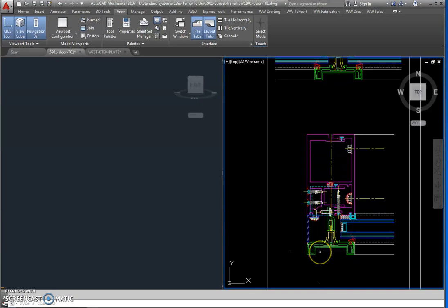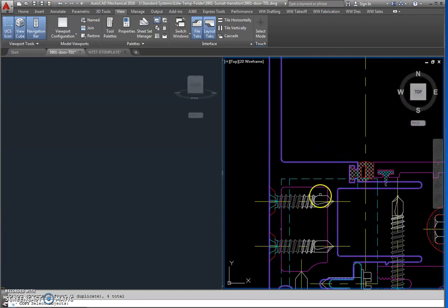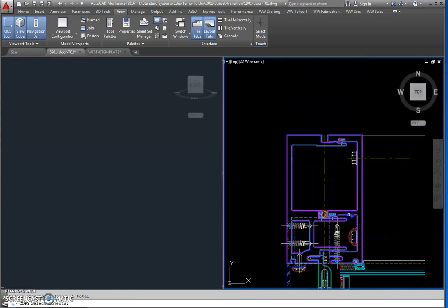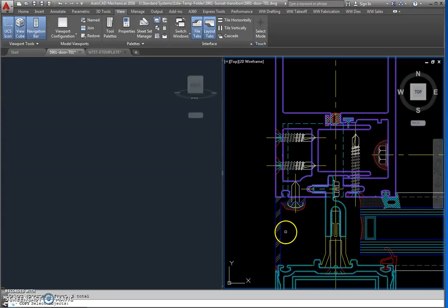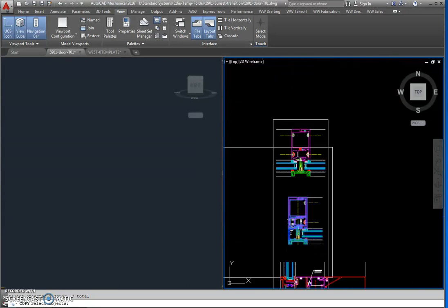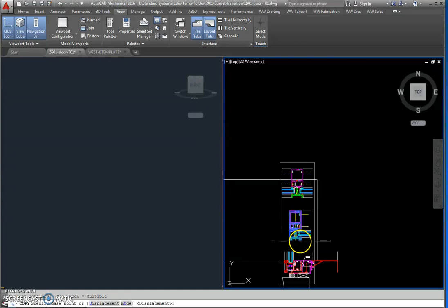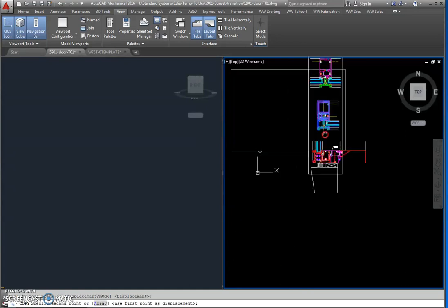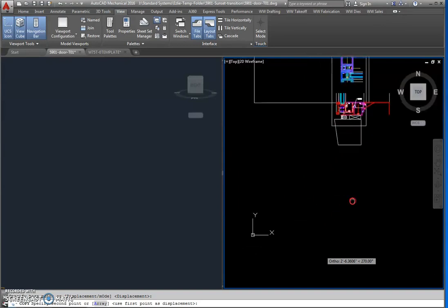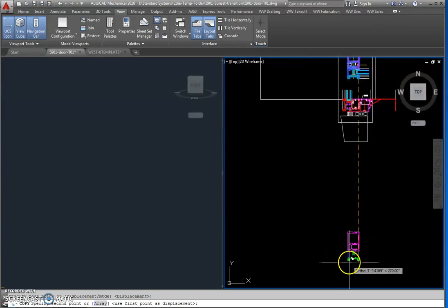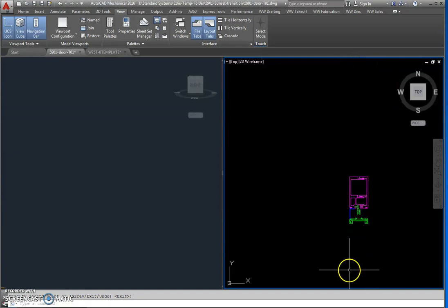So to start, we're going to copy those main extrusions, the vertical members. I'm going to take all of them here, and you want to make sure you grab the interior portions like this so that it becomes hollow later. I'm going to get the male and the female bodies and then the pocket filler. Okay, so I'm just doing a copy, still in 2D, and I'm just going to copy it somewhere down here in space. Again, it doesn't matter really where, just somewhere off in space down here. Okay, so just a basic copy of those pieces.